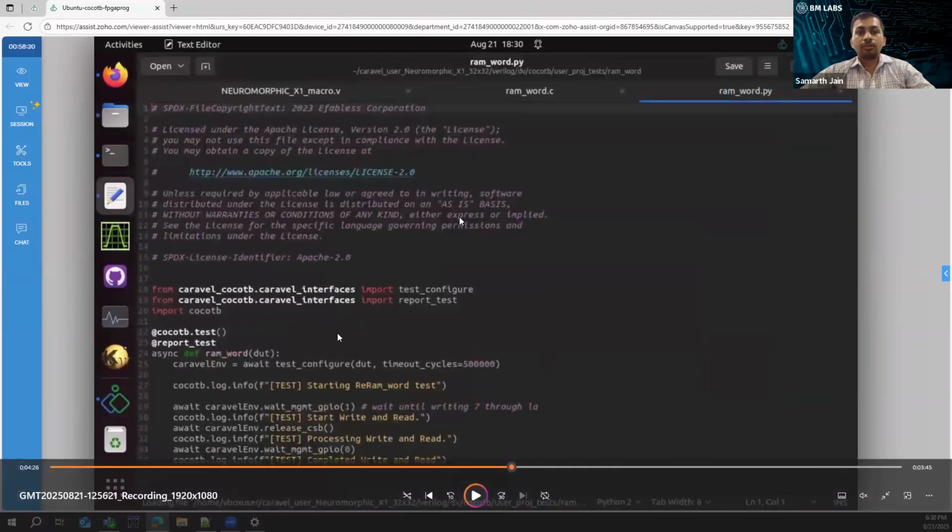Oh yeah, this is the Python script you were seeing. So it reads the GPIO status, right? I mentioned we are playing with the GPIO pins, right? When we are doing the read write operation, to know physically whether it is actually happening inside the chip or not, you can use this Python code to read the status of the GPIO pin and print the status and